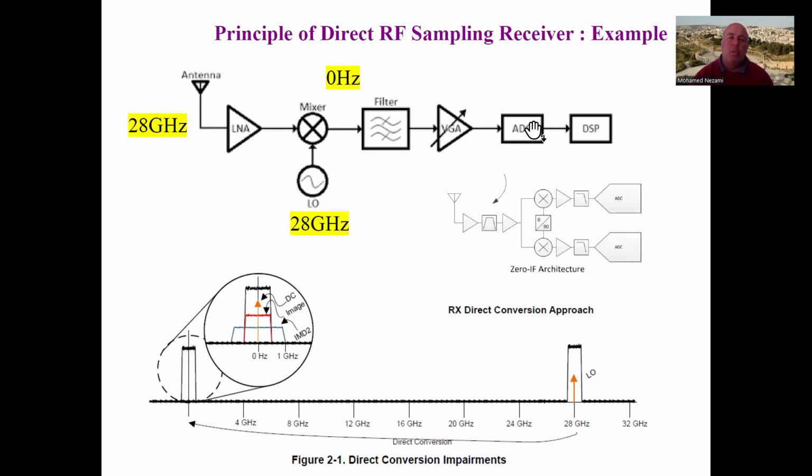So if it's within the dynamic range, then you have to perform some digital signal processing algorithm to try to take out that DC, which is basically you keep estimating the mean of the I and the Q, and you just keep subtracting an offset from both in-phase and quadrature branches.